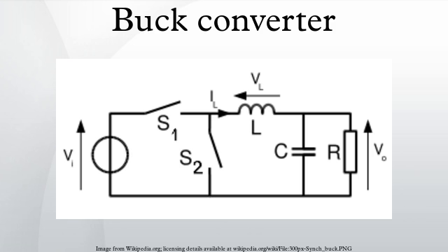The only difference in the principle described above is that the inductor is completely discharged at the end of the commutation cycle. This has, however, some effect on the previous equations. We still consider that the converter operates in steady state. Therefore, the energy in the inductor is the same at the beginning and at the end of the cycle. This means that the average value of the inductor voltage is zero. That is, the area of the yellow and orange rectangles in Figure 5 are the same.